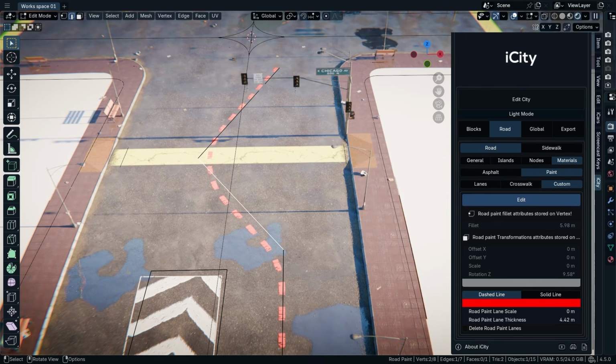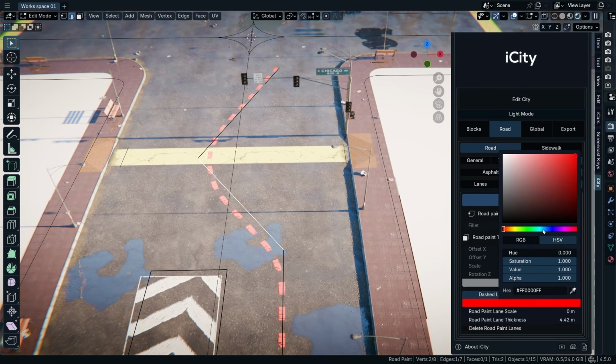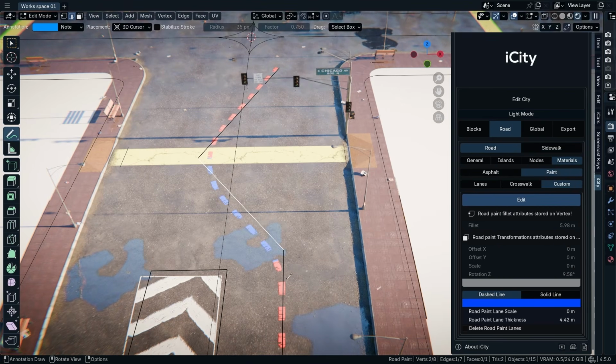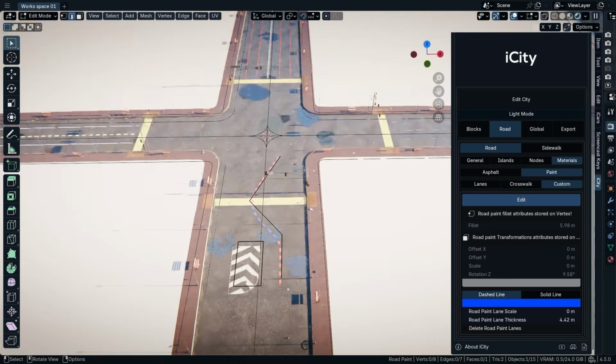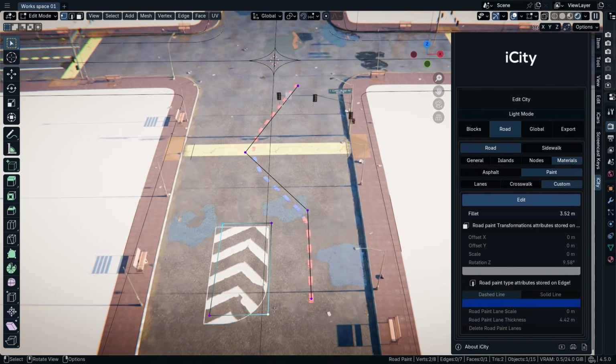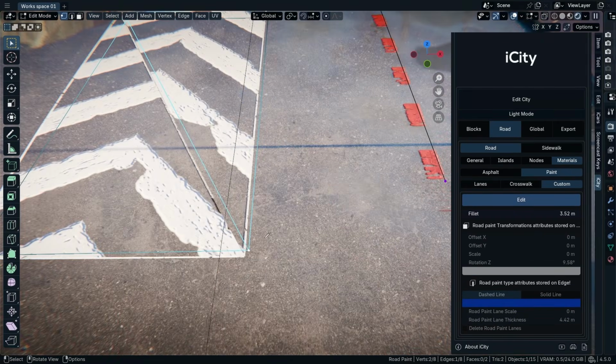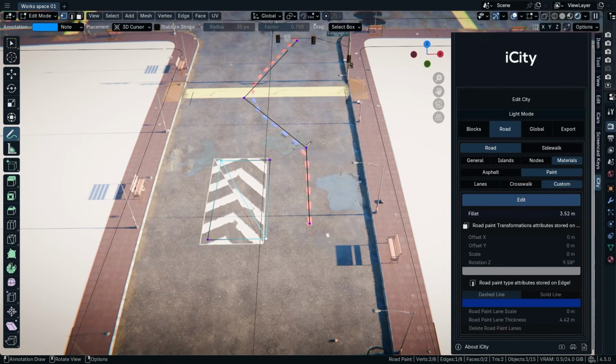You can give each one a different color. For example, this one, I want it to be blue. Now it's blending between red, then blue, then red again. Same for the face, you can just do this, which is going to remove the fillet. To use the fillet, make sure your point does have only 2 edge neighbors. Otherwise, it's not going to do the fillet.